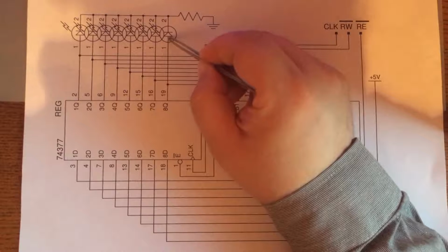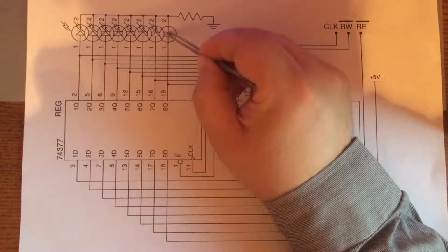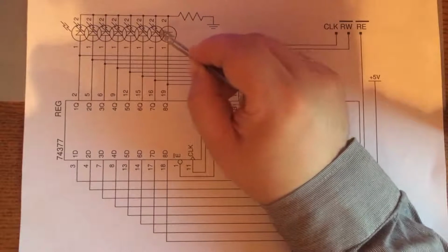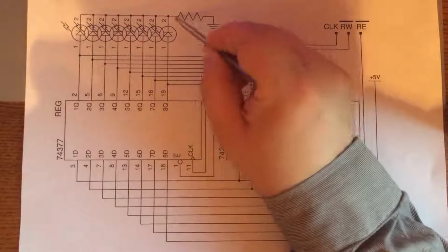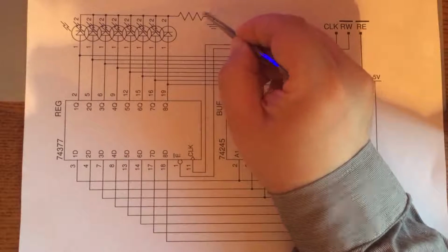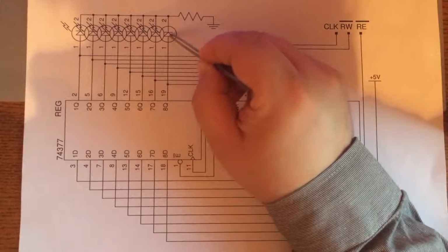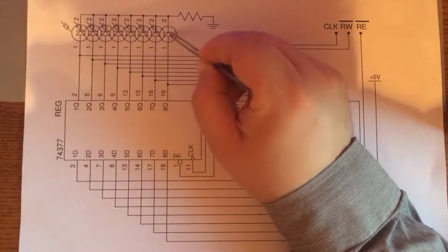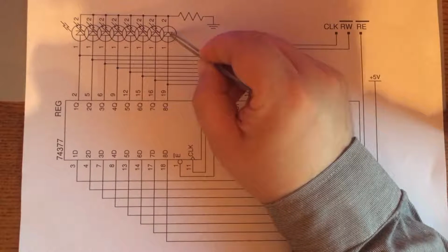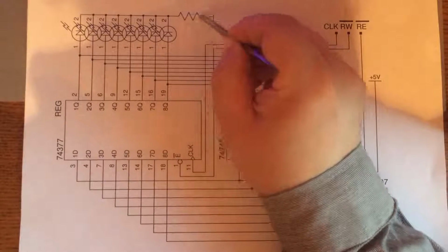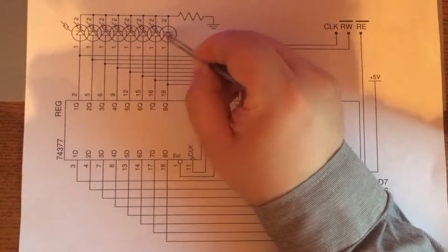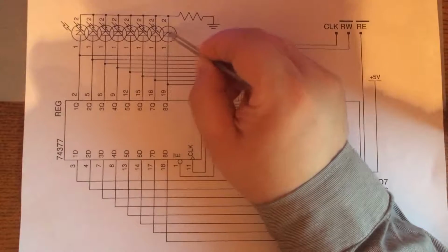And so if only one LED is on, well, then 20 milliamps will flow through that one LED. But if two of them are on, then we'll still have 20 milliamps through this single resistor, but we'll have 10 milliamps through each LED. And so they actually become less bright. And if I have 3 LEDs on, well, I'll be sharing my 20 milliamps amongst 3 LEDs. So I'll have 7 milliamps in each of them.